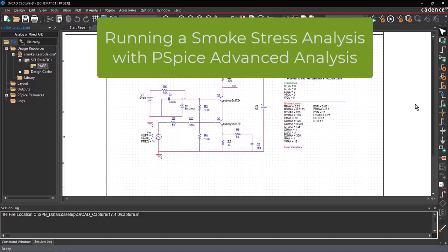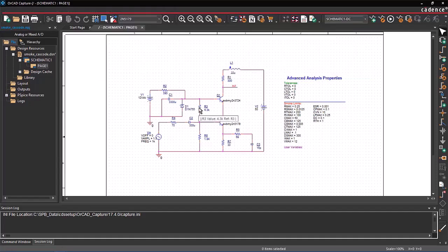Smoke uses maximum operating conditions supplied by vendors, and optional derating factors, to calculate the safe operating limits of a component's parameters. Smoke then compares circuit simulation results to the component's safe operating limits, and if the circuit simulation exceeds the safe operating limits, Smoke identifies the problem parameters.